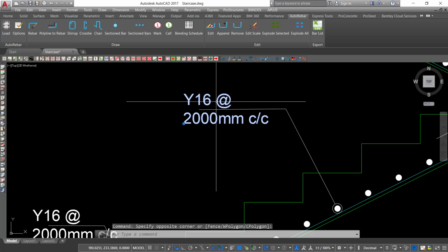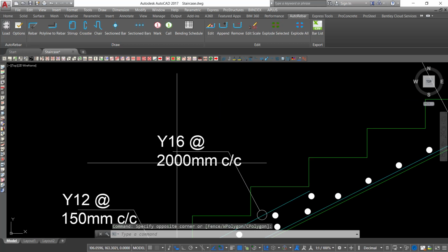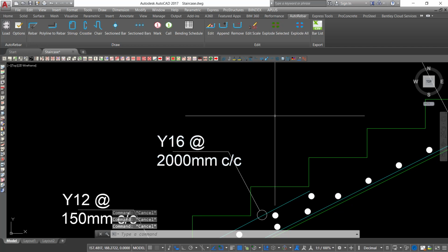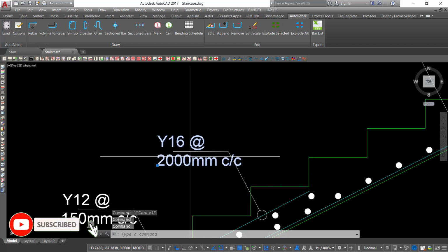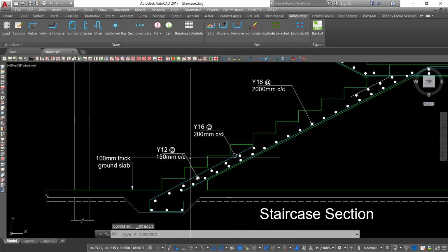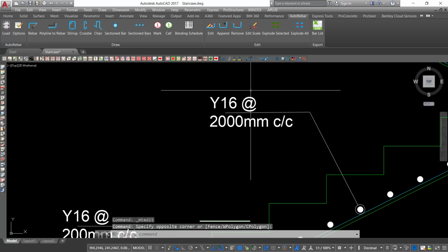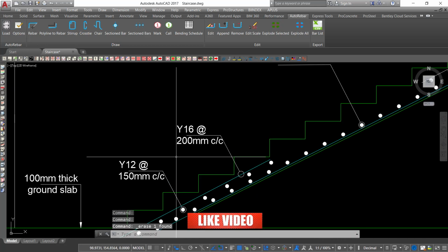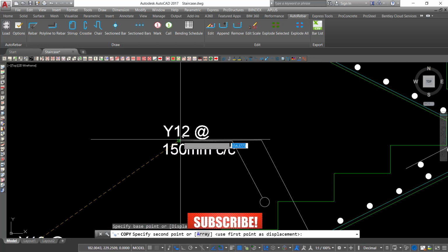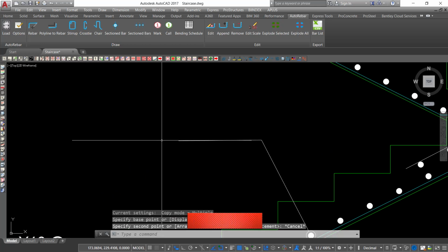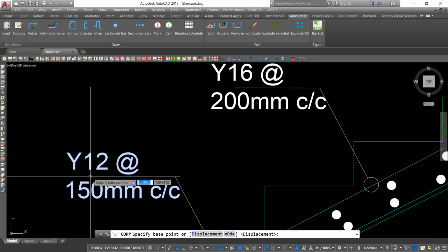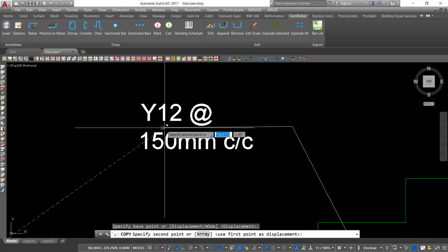Instead, this should be 200 millimeter, just escape that. So we get rid of 10, and we can carry this text all the way. You can carry this text instead of that. We don't want to write anything, and we can copy it from that spot and place it somewhere here. Just disable that, because we've copied even the arrow. Select on that and pick it from this spot, and we'll place it somewhere there.